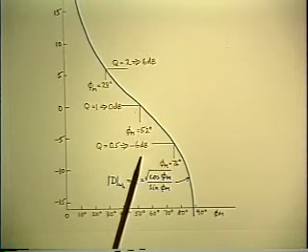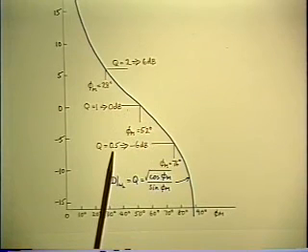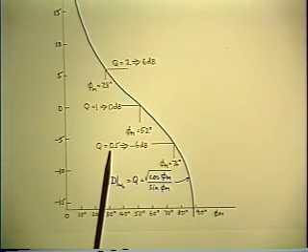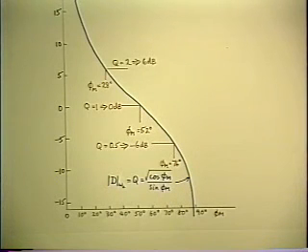If you want to be really safe, and you want the Q to be no bigger than 0.5, which means your closed loop quadratic has 2 equal real roots, and you're 6 dB down at the end of your closed loop bandwidth, you've got to have 76 degrees of phase margin.